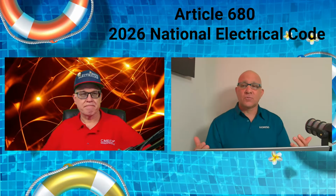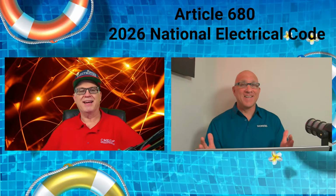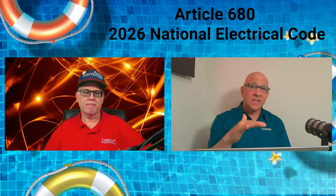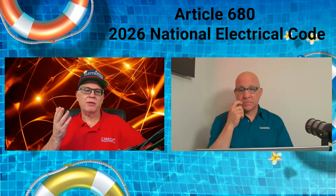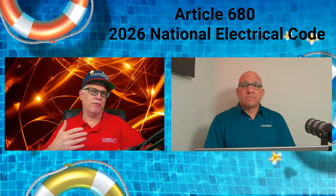People are familiar with 120 volts. The concept is if we put everything at the same voltage, so if we put everything at 120 volts, it eliminates any step or touch potential difference. Especially with these pools, because we're probably not talking about anything near that. We're probably talking 3, 4, 5, 6 volts.